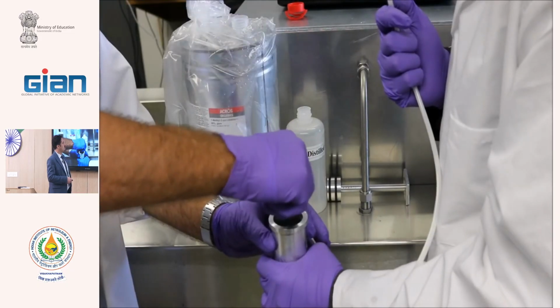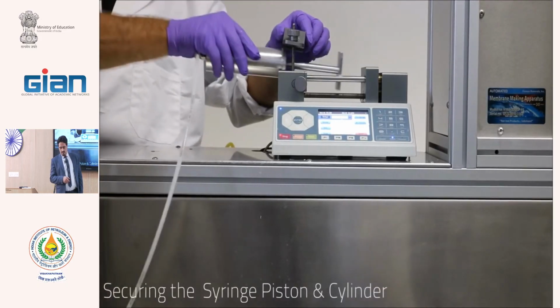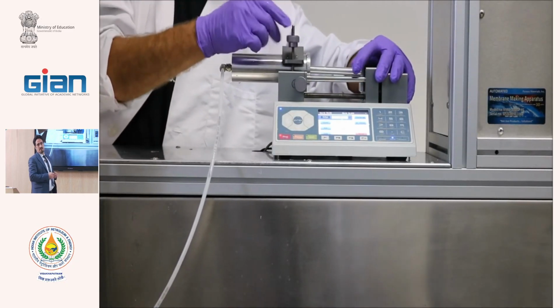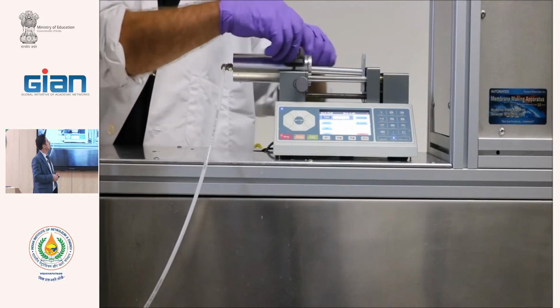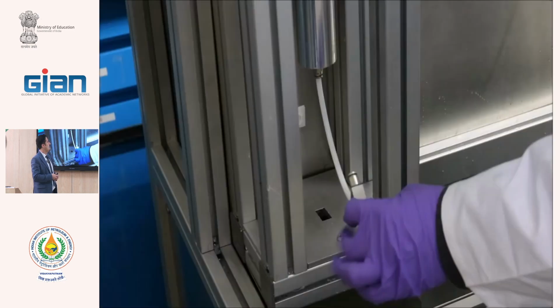Fill the cylinders for injection. In hollow fiber, we have bore fluid. That bore fluid should be inserted in the spinneret for precoagulation and producing the hollow fibers, through the lateral tube. This is the injection pump.